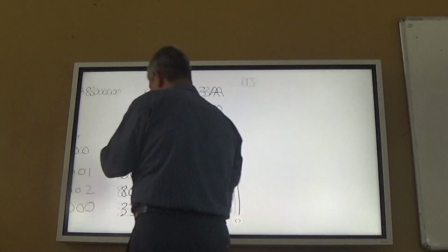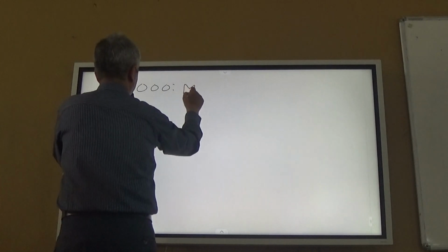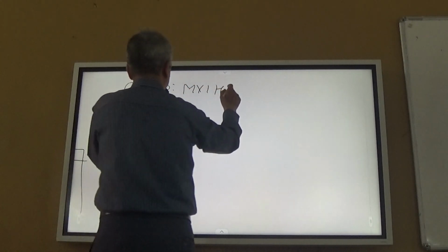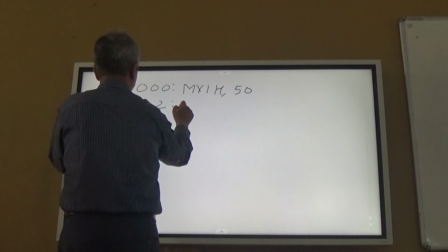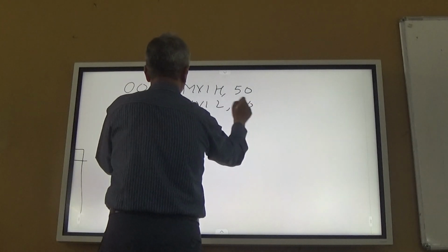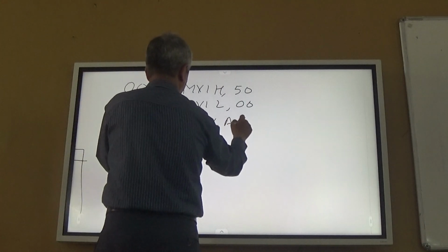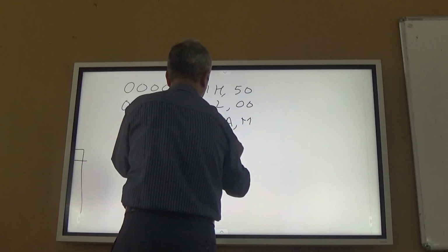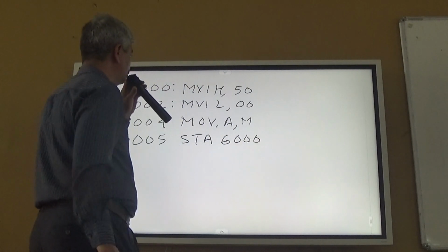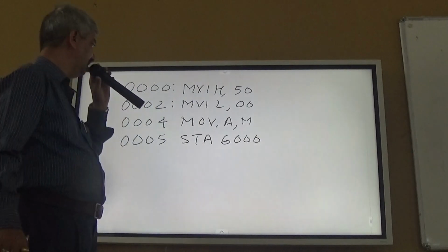Now I will use the next program. So MVI H, 50, MVI L, 00, MOV A, M, STA 6000.